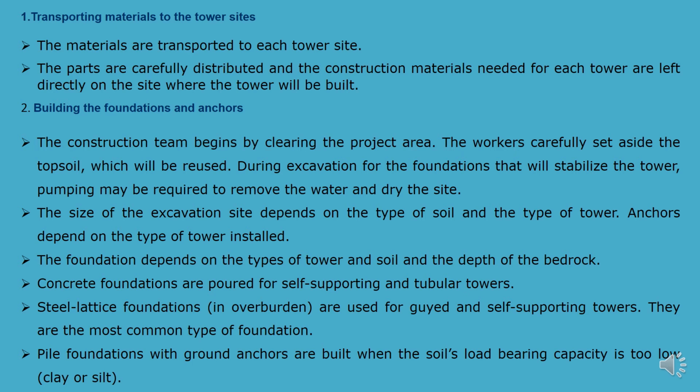But suppose if it is excavation, right, it may be 2 meter or 3 meter, right? So in that particular area, there is some chance of dewatering also, right? So dewatering means you just have to remove the water from the trenches, and particularly that area should be in dry conditions so that we can start the foundation.